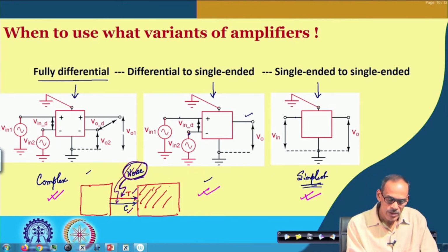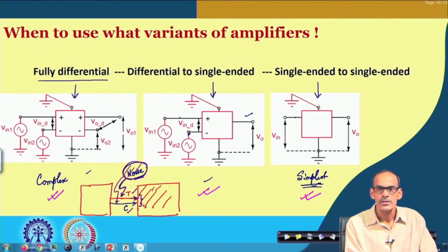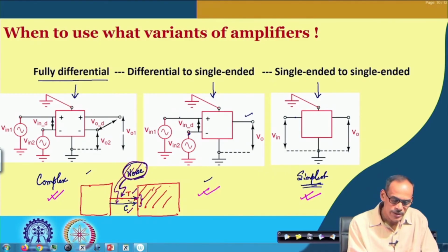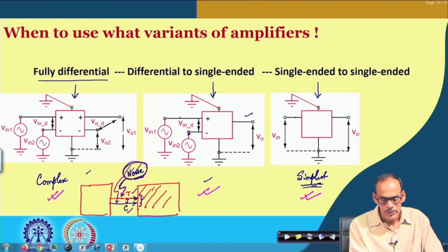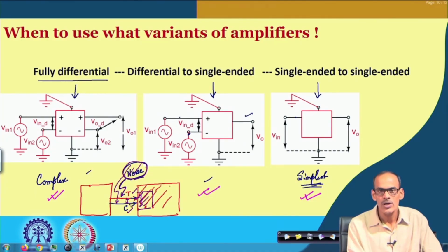So, the received signal, if you see here, the noise can be received like a common mode signal, and the difference of these two line voltages can be treated as the main signal, which is differential. So, whenever we have some block here which is first interfacing with the external world, particularly whenever we are receiving a sensitive signal, and in case it is getting affected by noise, we like to keep the first block, at least its port, differential in nature.